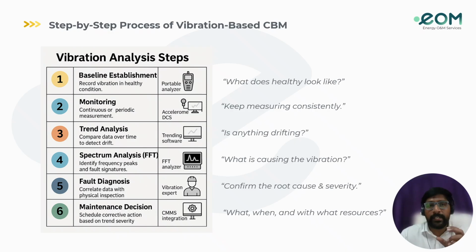Then here the spectrum analysis will come into play, converting time signals to the frequency domain to identify the fault mechanisms. And the next one is the fault diagnosis, meaning confirming the root cause and severity. It helps with vibration findings, also temperature findings, and also oil debris, and also ultrasound and motor current.